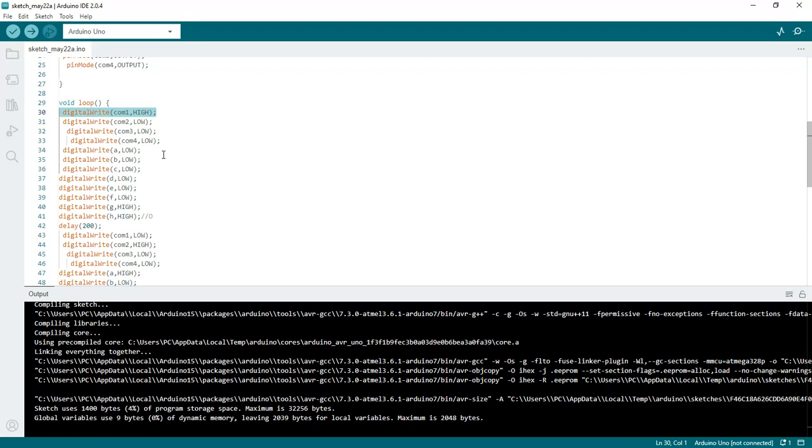Your 7 segment will hold for some time even if you remove the supply, which means by deactivating your common pin with the logic. And if you write the same values again in the loop, it allows handling the same number again and again. So while giving the number to the first digit, make sure the first common pin is high, the other 3 common pins are low, and provide your number.